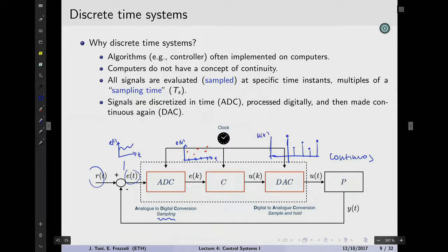so it's just a collection of points. In order to transform it into a continuous signal through the sample and hold, which is a first order, let's say, conversion, all we do is take, at the specific sampling period, whatever the value is, and we keep it: we sample, and we hold it, we keep it constant up to the next sampling point.